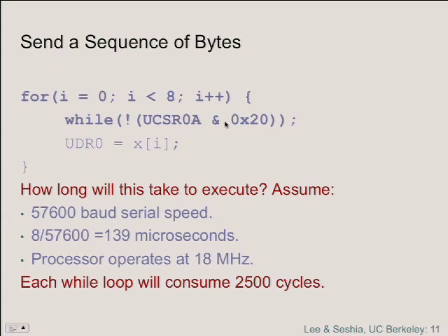So, one strategy would be don't talk to the serial port in an interrupt service routine, or do all of your talking to the serial port in interrupt service routines only, okay? And carefully control how they're architected. Think about what's doing what when, and so on. So receiving via UART is similar, except that's what I thought the original code was doing, right? But this is just you're looking at a different bit in that status register.